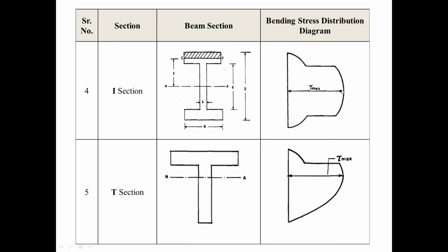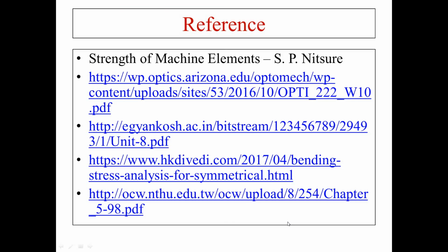At this level also it is varying, because the area is more, so the stresses will be more. From here we have to take down the whole area, so that's why the stresses are more. So it is symmetrical. The upper section and the lower section are symmetrical. For an unsymmetrical section, at this point 0, and at this level we are having two stresses, one for maximum width, another for lower width. At the neutral axis there is more area, so that's why maximum stresses, and here there is 0, so it is varying like this. So that's it.